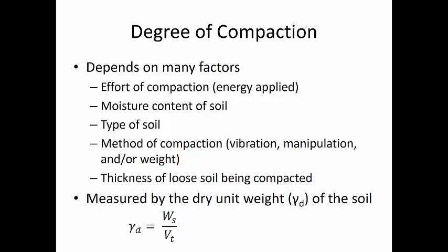But there are other aspects to this that play a role, and that is mainly due to the amount of moisture in the soil. The correct amount of moisture will allow the contractor to achieve the compactive effort necessary on that project easier, because the water allows for lubrication and rearrangement of soil particles, especially in clay soils.